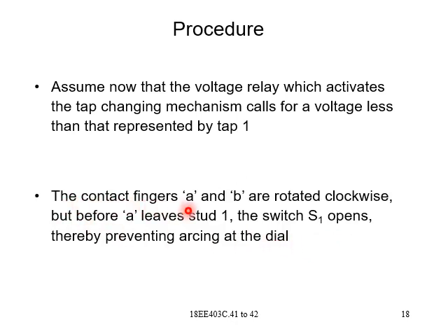The contact fingers A and B are rotated clockwise, but before A leaves stud 1, the switch S1 opens, thereby preventing arcing at the dial.